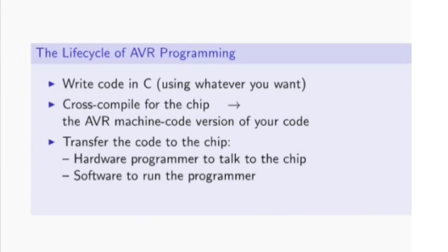And the AVR chips want to be programmed using the SPI protocol. And so what you need basically is something in between your laptop and the AVR chip on your breadboard that speaks the SPI protocol. And this is what I'm going to call a hardware programmer.